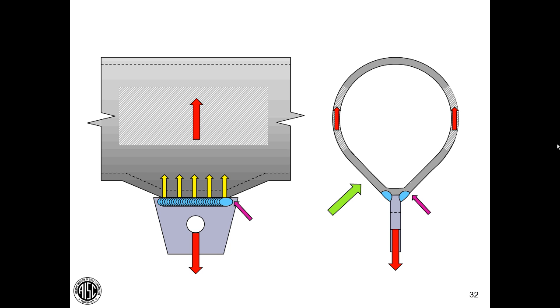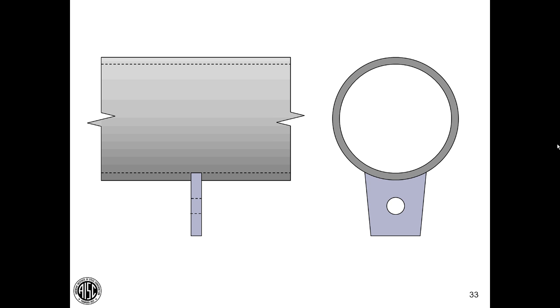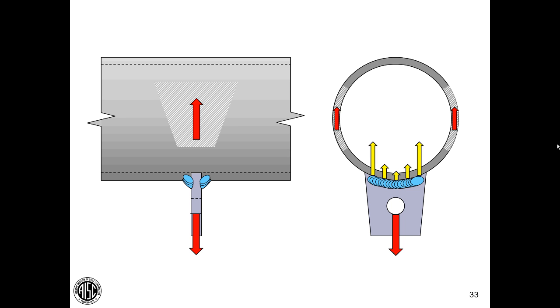What if we rotate the lug 90 degrees? We put in those welds, apply the vertical load. The parallel portion is still at 9 o'clock and at 3 o'clock. Do you see that we still have a problem with this connection detail? The ends of the welds are going to be most severely stressed because they're trying to transfer that load over to that 9 o'clock, that 3 o'clock location.